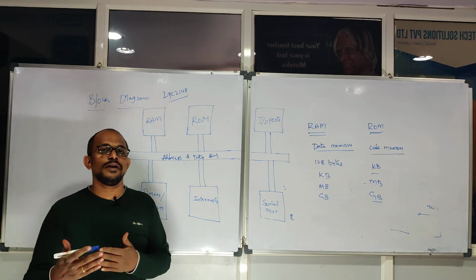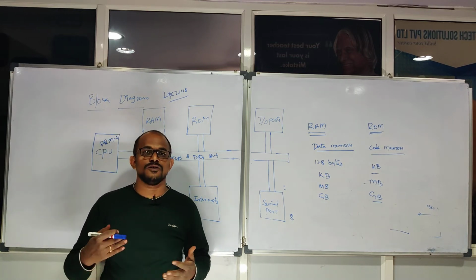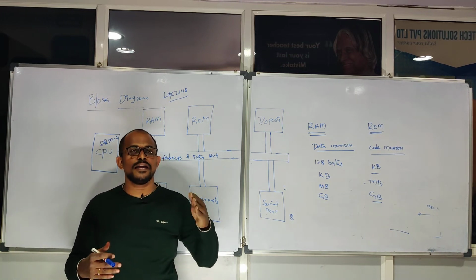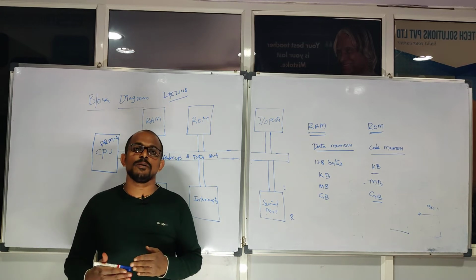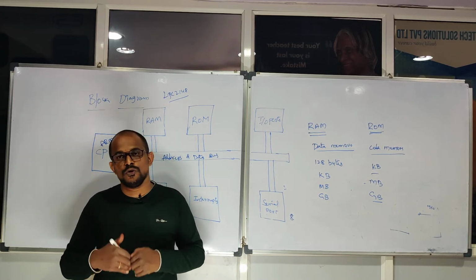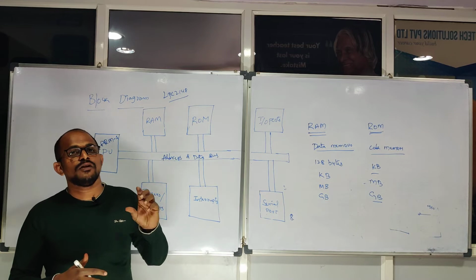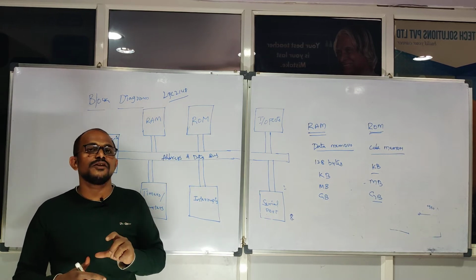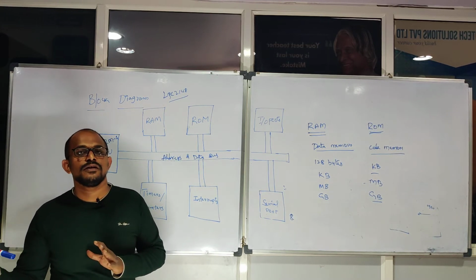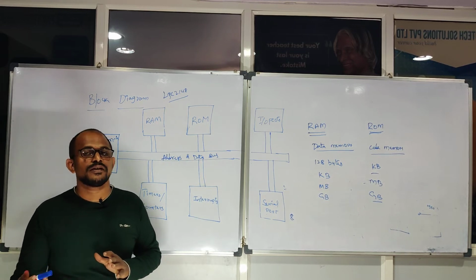So you need to provide some delays between logics. If you keep logic high, then you need to apply a delay and then logic low. If you make it logic high and logic 0 in the next line of code, your external peripheral is not going to respond in that short a time.